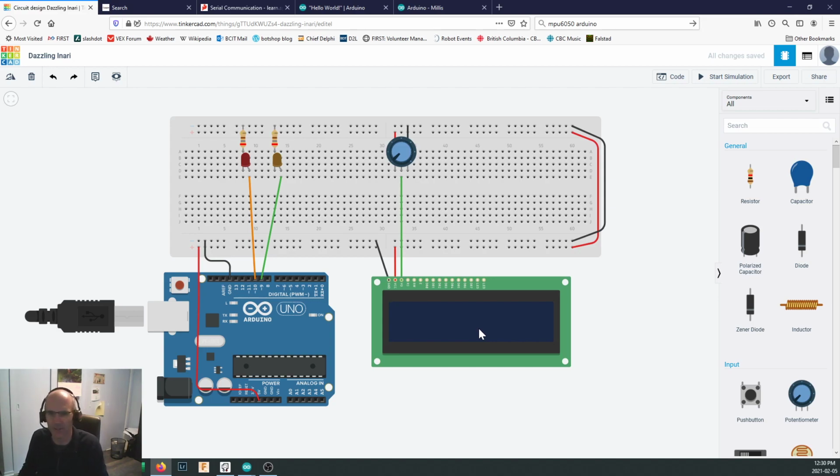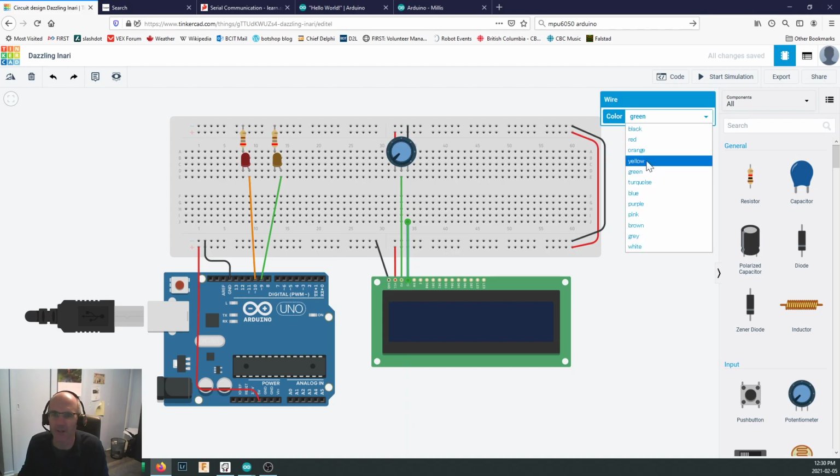And I'm going to use a yellow line coming right in here. And the yellow line is going to connect to our, where are we here? Our RS, our register select, which is right in here. And I'm going to run it this way because this is how we do it on our big bad breadboard board, but you could go straight to the Arduino.